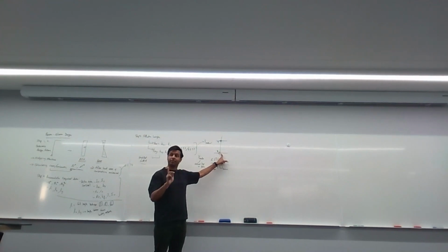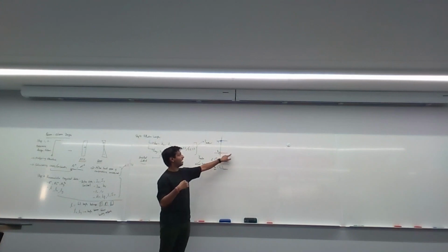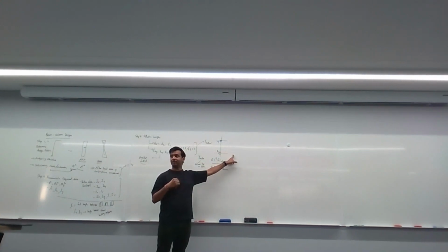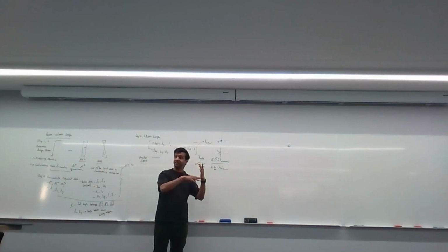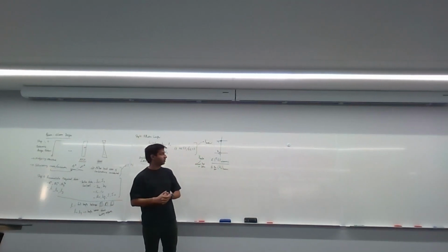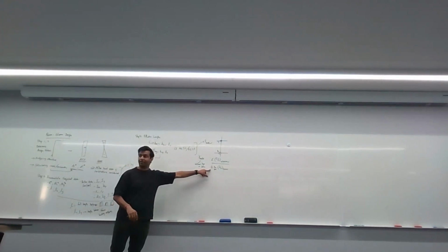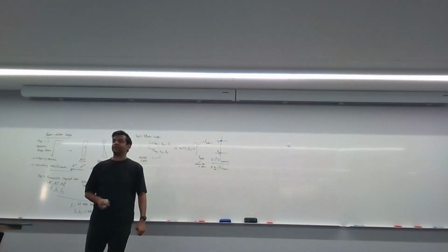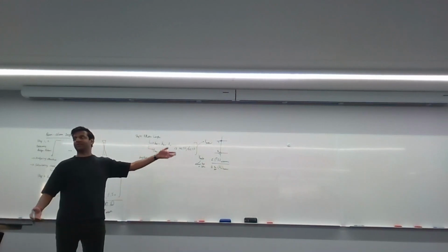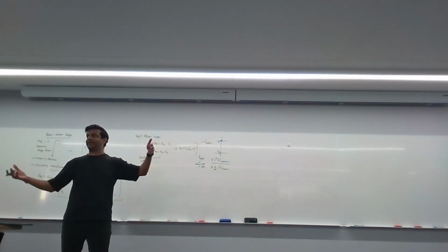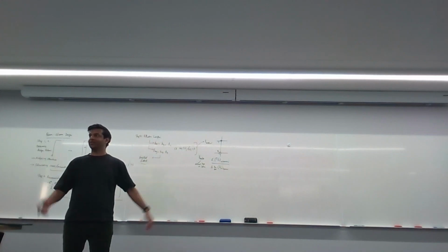But beta E also depends on the connectivity of the beam on the far end, that means on the other side. Is it fixed into a wall? Is it pinned over there, etc.? Based on these two, you can select your beta E parameter and make sure that's used in your calculations. Revise exactly what the correct beta E is to use, because it's a waste to do all of these questions and get all the numbers correct and then get it wrong because beta E was wrong.